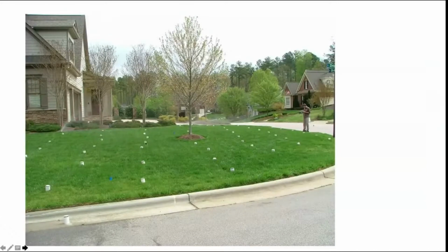Okay, so here's another example of a house we did an audit of, laying out the catch cans. We generally would take a different color flag, have a common color per zone, and then use a different color flag for a different zone. There's no set rule on the spacing, 2 meters is usually sufficient. You want to have a number of cans between the sprinklers to complete your array. On golf courses, you can space it out a bit more because you can get into hundreds of cans if you're doing a fairway.